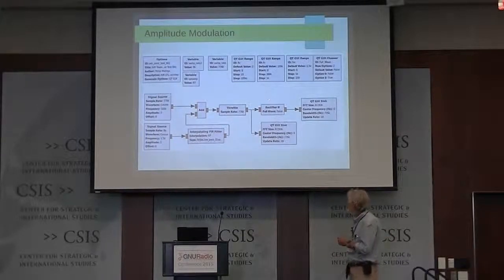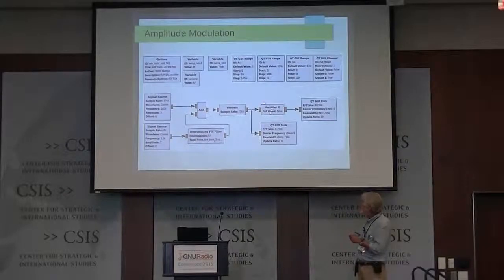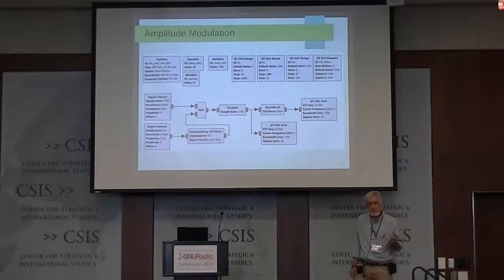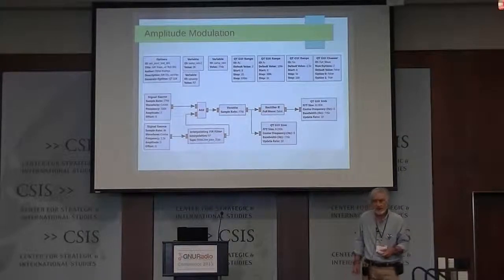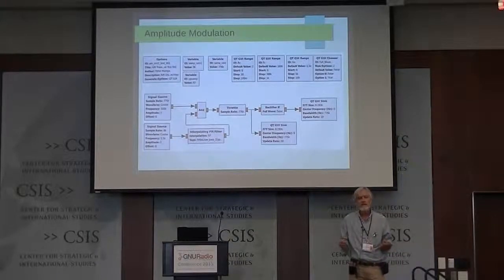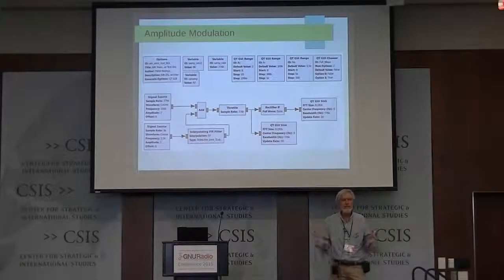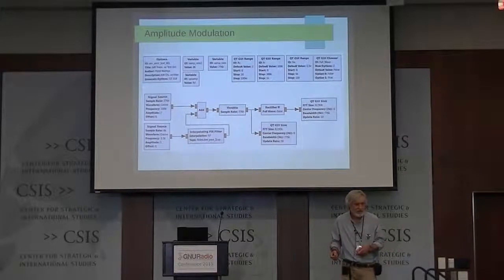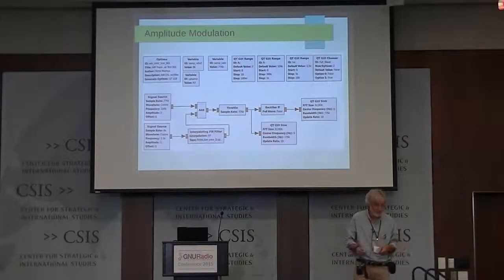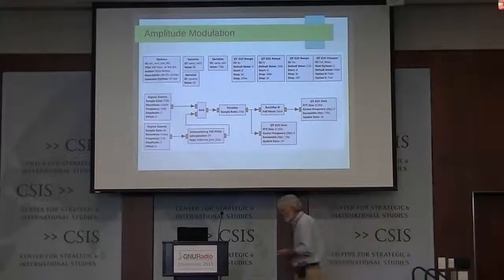So the nonlinearity is this block in here. In this particular one, I use the rectifier again, either the half wave or the full wave rectifier, and then I can ask the question: is this going to produce amplitude modulation with transmitted carrier or with suppressed carrier, and at which frequencies? I'm not going to go into all of the details here.